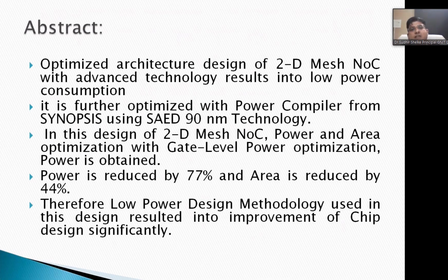In this design of 2D mesh NoC, with power and area optimization at gate level, power is reduced by 77% and area is reduced by 45% compared to the generic architecture of 2D mesh NoC. Therefore, I can say the low power design methodology used in this design resulted in significant improvement of the chip design.